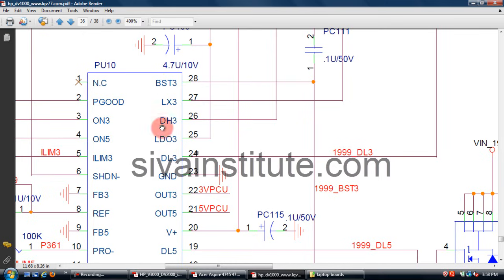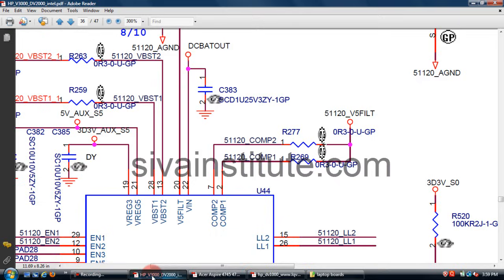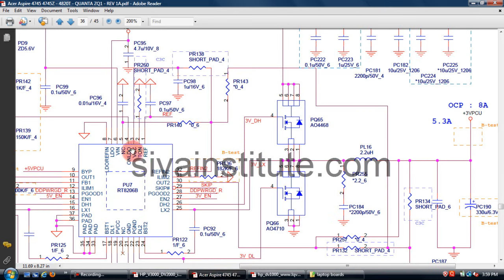One is this one, V in plus shutdown pin. You should check these 2 pins. In the first model, you only give this V in, and the voltage will come out from this IC. There is no shutdown pin here. And see here, the LDO in pin.